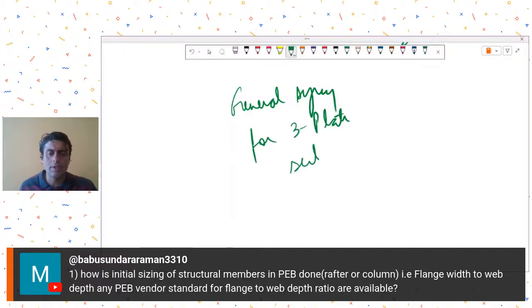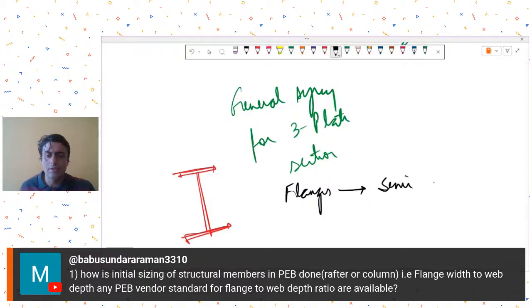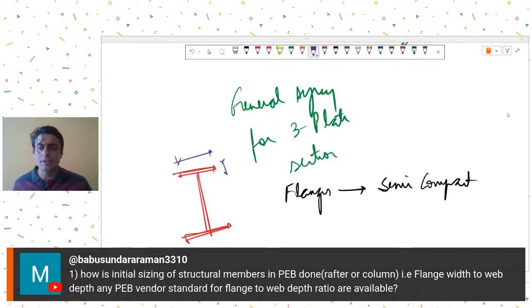Because most of the pre-engineered structures are made in three plate sections, where you have a flange, a web, and another flange. So what is the general strategy followed? That is the query. What most of the times the strategy that is followed is, and we have discussed it in our PEB course also, that for flanges generally semi-compact flanges are used. So the flange width to thickness ratio will be such that they get classified as semi-compact sections as per Table 2